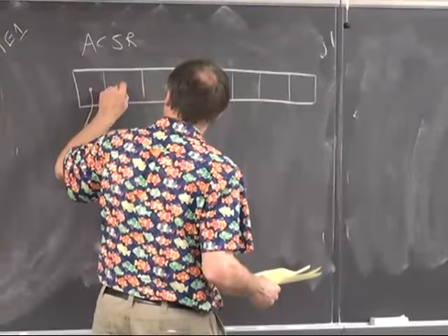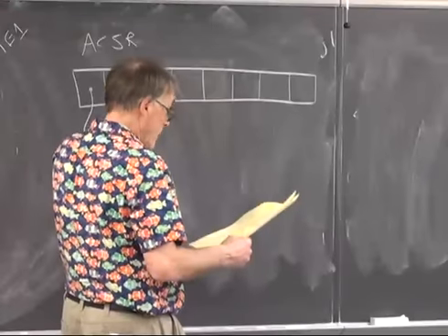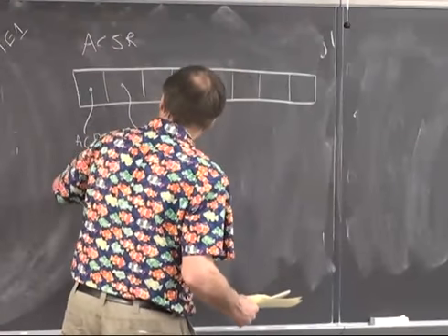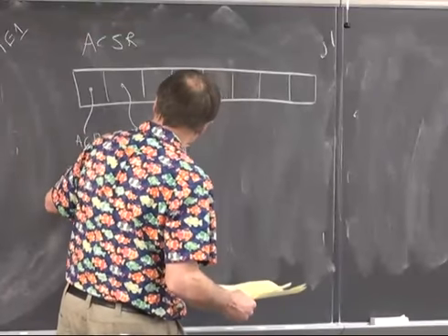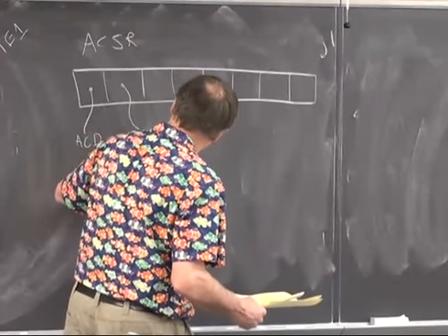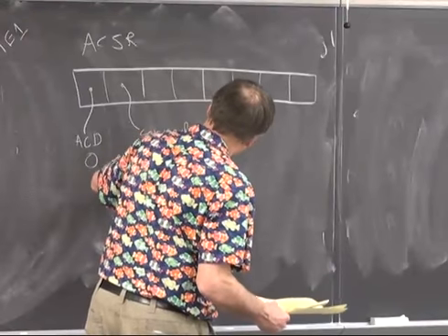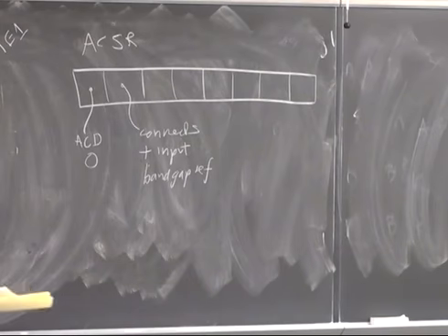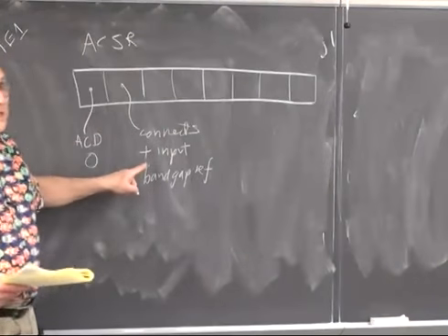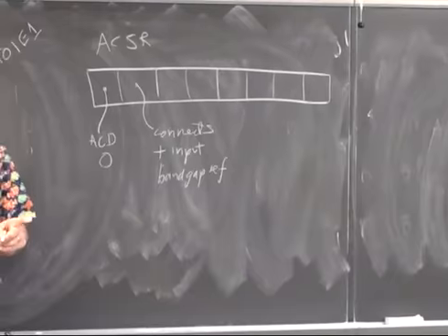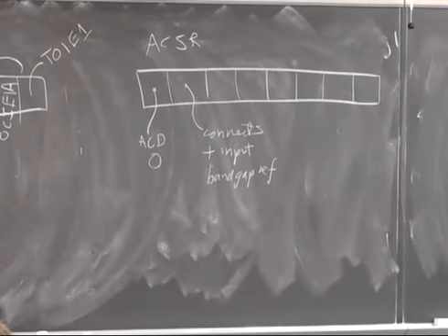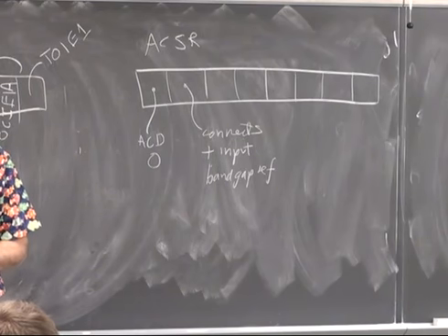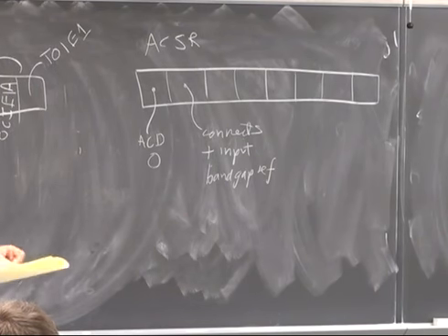Bit 6 connects the positive input to a band gap reference. So if you turn this on, then B.3 no longer goes to the outside world. It goes to a band gap reference instead. You don't want that in this case. Actually, you could use that. It's your choice.